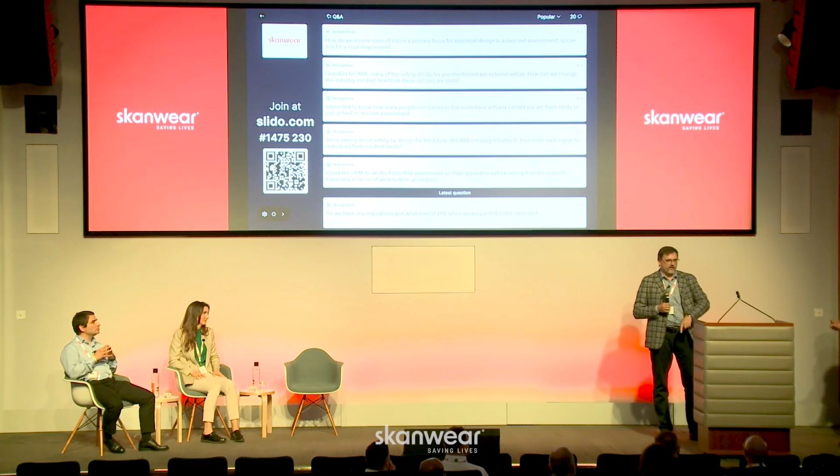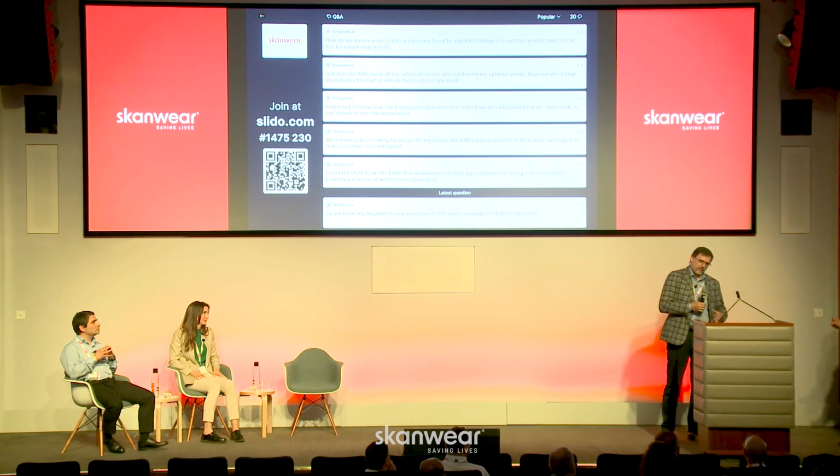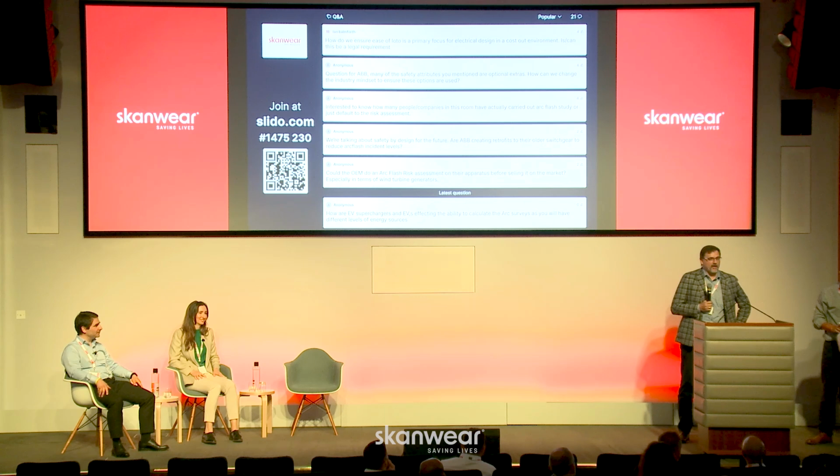Well, I can tell you one thing: you have it. The thing is that you don't look at it from an equipment perspective, but you have to look in BS EN 50110, because it is there. There is Annex B6, all about arc flash, and I think there is a new 2023 or 2024 version of it. So it's not that you don't have it; you actually have this requirement. That was the previous question: is it legally required? You got the biggest fines in Europe, mainland, yeah. You are still in Europe. Maybe not in the European Union, but in Europe still. So you have it.